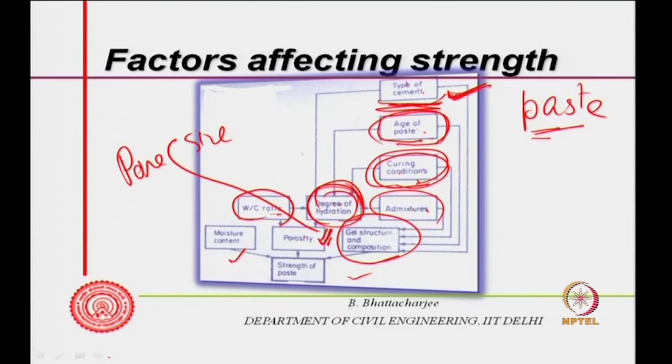Also, degree of hydration is controlled by water cement ratio, and water cement ratio also governs the porosity. Then the gel structure would depend upon all these factors, and finally, the moisture condition. All this actually governs the strength of paste. So, this is the strength of paste.